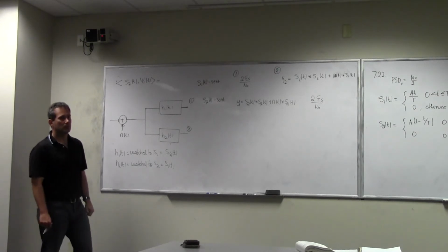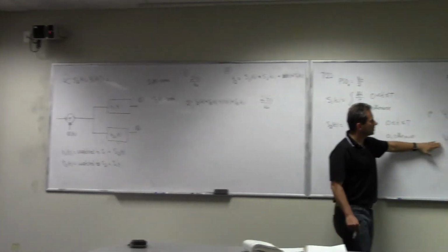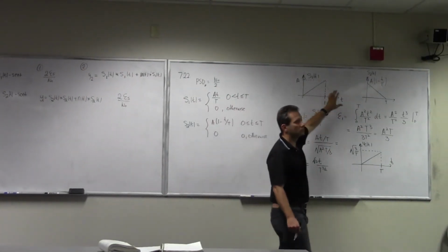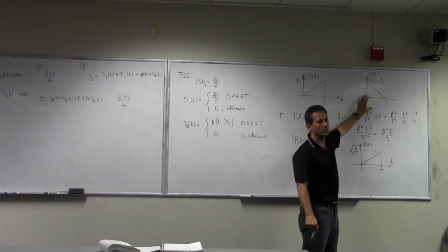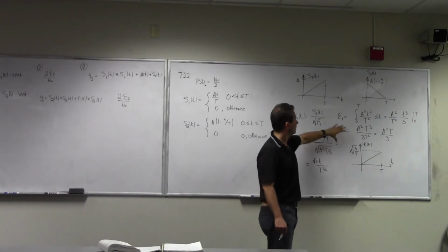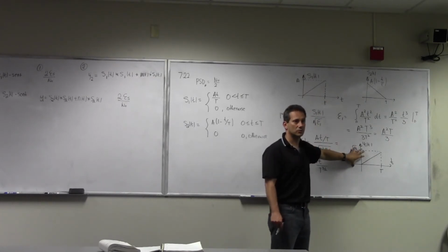So you're going the route of a correlator? I'm going the route that we demonstrated in class that is optimal. I realize these two are not orthogonal, so let me extract the orthogonal basis set. I started with the first one, got the first vector, and I'm going to get the other one, which is orthogonal.